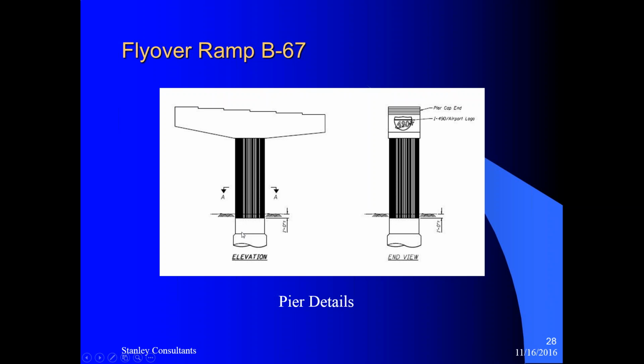This is to minimize the impact on railroad operations, and one caisson could be constructed in a day or two, 3 days maximum. So that's a very quick, very efficient system. However, when you have a single column, single caisson foundation, the pier is a little bit more flexible. So then the deflection of the pier is a little concern.